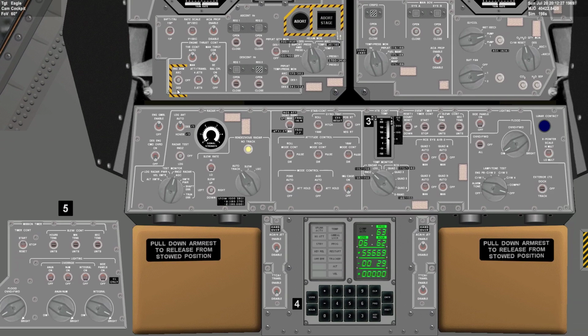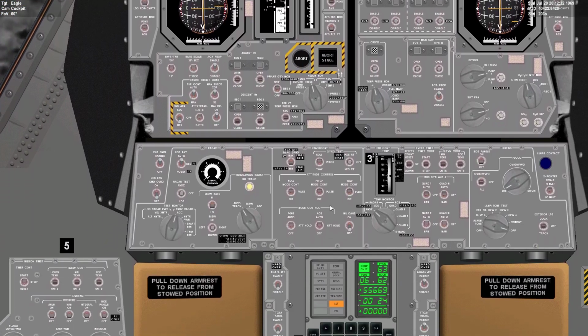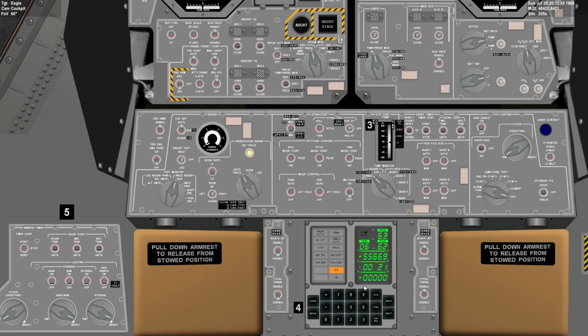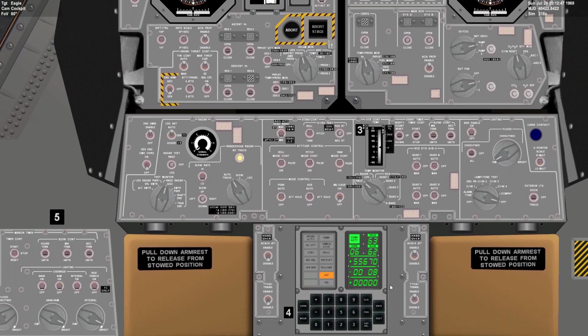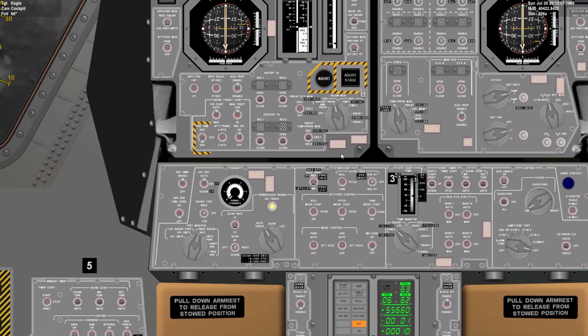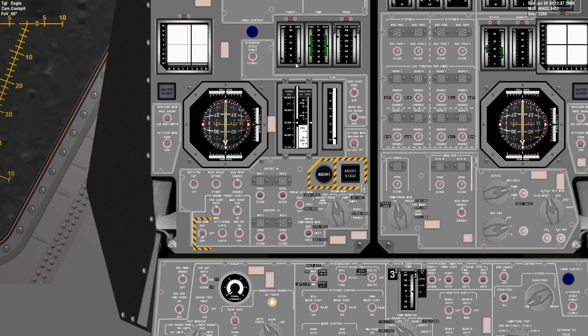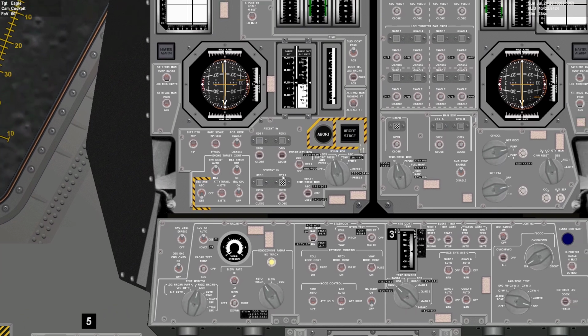So what I ended up doing was generalizing the logic that I made to inject DSKY key presses. And so now I can use that same logic to inject any type of interrupt and not just the DSKY key press interrupt. So that can now inject hand interrupts. I don't have it running right now, but it can inject down interrupts. And the other thing that is needed for a landing is descent engine command override on. I forgot to switch last time.